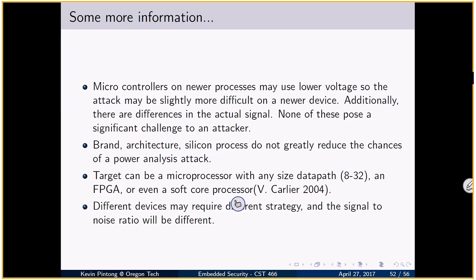Well, the FPGA is not faking hardware implementation. It is actual hardware. It's actual silicon, right? So the FPGA is just reconfigurable hardware, right? So when you have that reconfigurability, what's the problem with the FPGA versus a real microcontroller? Instantiating a soft-core processor on an FPGA versus a microprocessor.